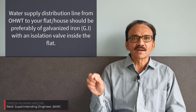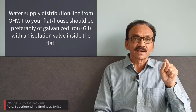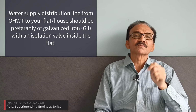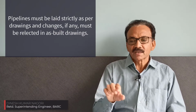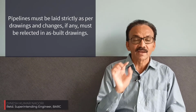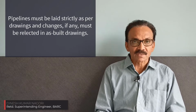Now coming inside your flat, the moment this water supply line enters your flat, there must be an isolation valve which can be operated inside the flat, so that in case of any leakage you can simply close that valve and your work will be easier. That is the first requirement. The second requirement: whatever layout you are doing must be properly written on the drawing. If drawings are already there, you should follow the drawing strictly. If drawings are not there, at least draw whatever layout you are doing and keep it ready for future reference.